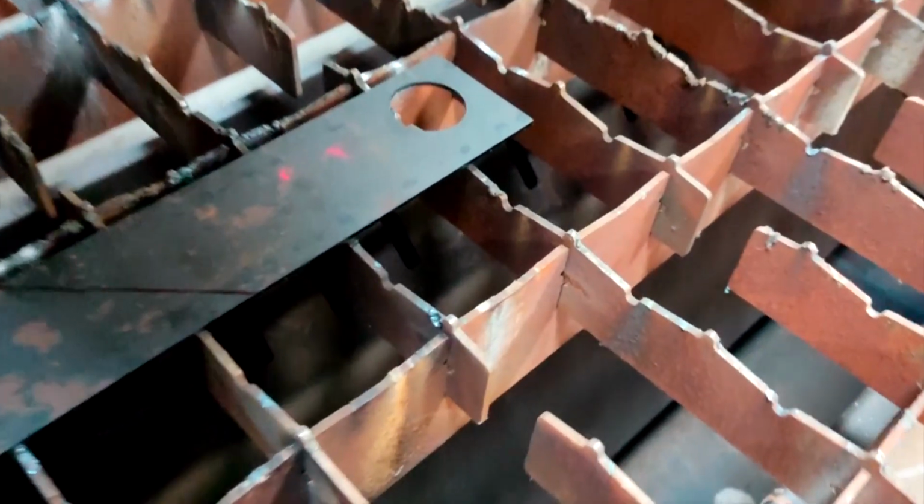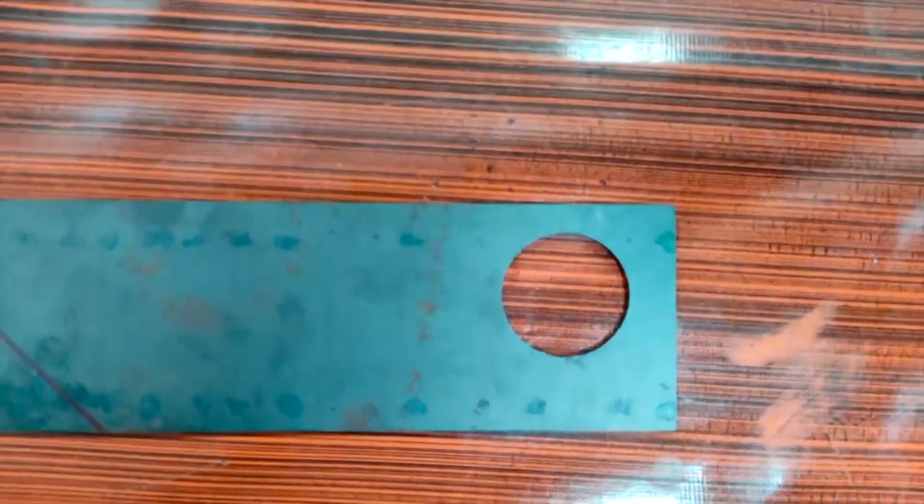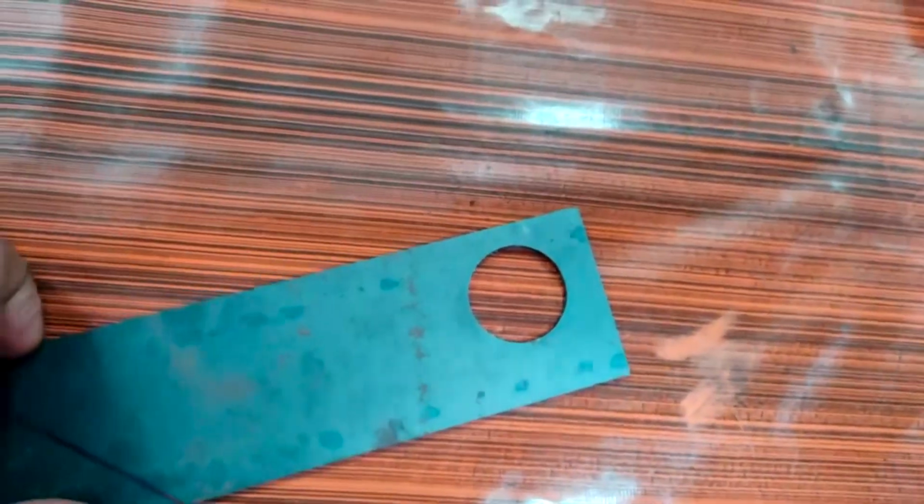So let us look at the job which has been done. Perfect. So we got a very good quality circular laser cut on a mild steel 2 mm thick steel plate. So this is the top view where the laser was applied. Now let us observe the exit. So at exit we got some sort of deposition or some sort of dross at the bottom, which can be removed by using a grinding operation.